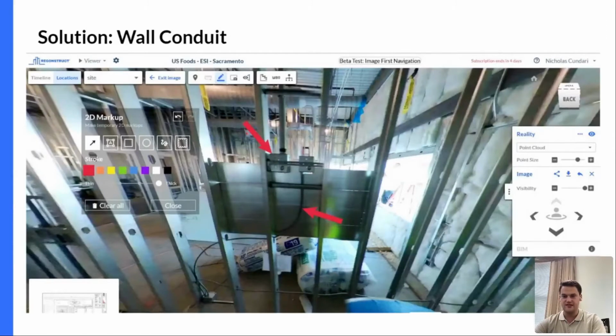Reconstruct helps catch the little details that not a lot of people are going to see. One of the biggest issues was our in-wall conduit. It was actually a floor box for our electrical floor box that was going for the interview room. When they poured it and then put up the drywall, our electricians forgot to put the conduit all the way up to the ceiling to where they can feed the wire in. And so a big issue was everyone forgot where that floor box was coming.